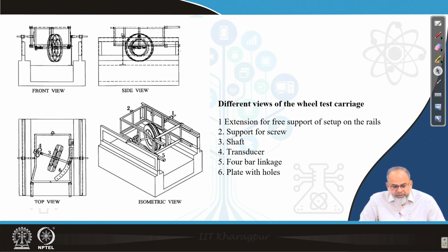For the experiments we conducted, first we developed a setup where you can vary these parameters. The parameters are the slip angle, the normal load, and the inflation pressure. We are talking about the contact patch, the lateral force which is developed at the contact patch. Obviously, the normal load and the inflation pressure are both responsible for developing the contact area. The more the load and the lesser the pressure, the more the contact area. So, the setup which we developed, I have given you different views.